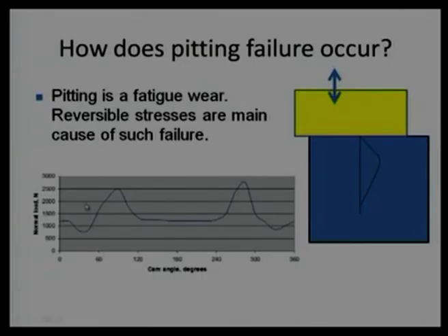So, first we did an estimation of the force which is getting transferred from cam to follower, and the cam is also experiencing a reaction force. So, this force is changing with the rotational angle. As the cam rotates, it experiences different kinds of forces. You can see here the force is roughly 1200 Newton, steady for some time, then it goes down, then goes up. Maybe the maximum value in this cycle is at 90 degree. At 90 degree, the load is high.